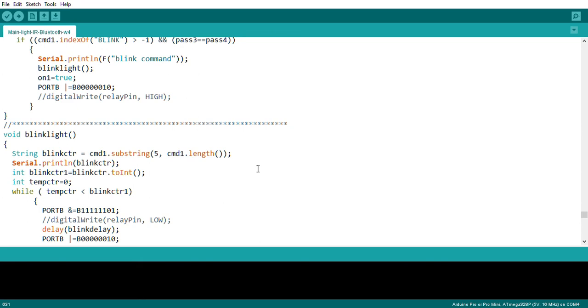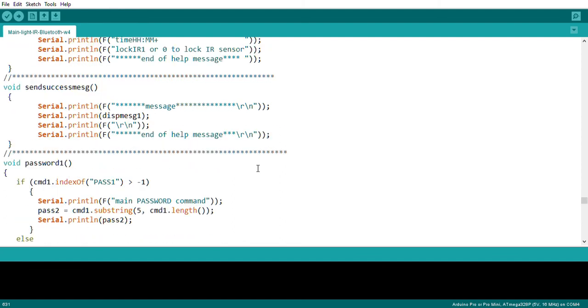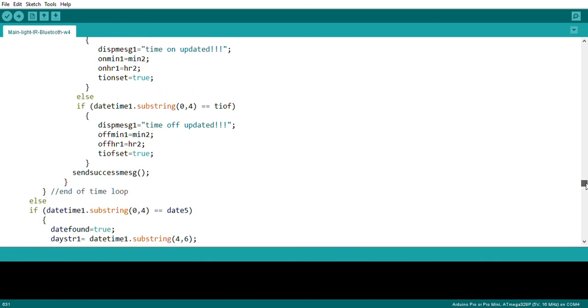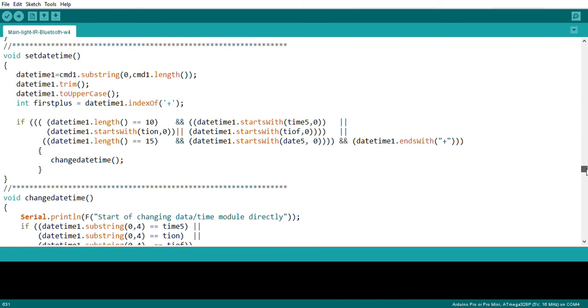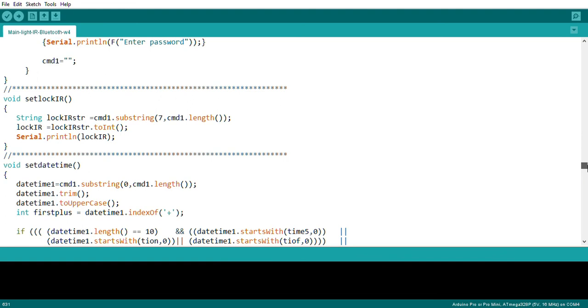future planning. You can even interface with a light sensor, an LDR sensor, which will read the sensor, calculate and estimate the evening sunlight time, the sundown time, and based on that you can switch on the light also. So that part can also be done. Apart from that, it can store the previous status, because if there is a power failure, when the power comes back, the Arduino will check the previous status, and depending on the elapsed time, how much time has passed, it can switch on and switch off the light. So even that can be done.